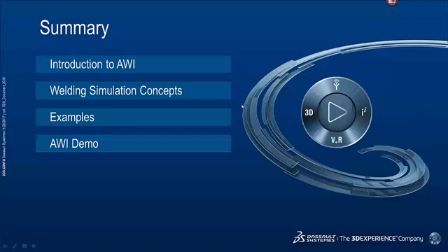Is this the offset parameter when setting up the heat source? So there was a question. Yeah, the offset is part of the Goldak parameter input. So you give your A, B, CR, and CF, and there is an offset. That offset basically sets the limit for the extent of the material to be activated ahead of the torch, and that's applicable both in the thermal model and the stress model. But as I mentioned briefly, in the stress model, we use a slightly smaller value of the offset.